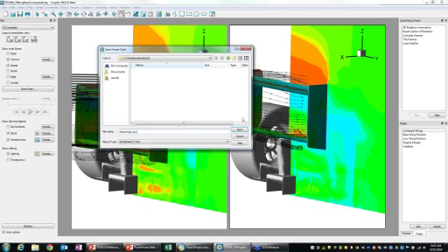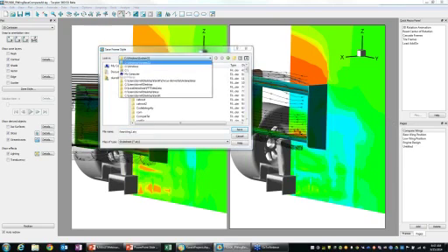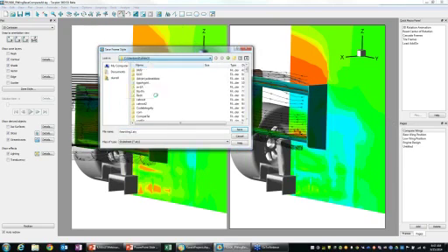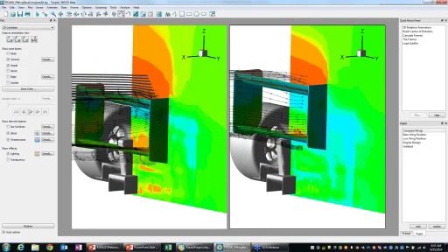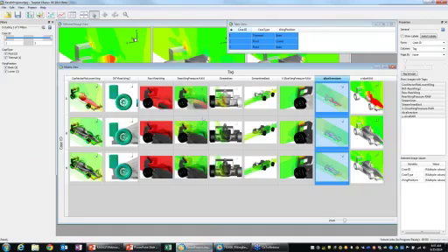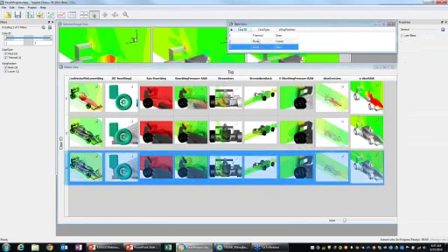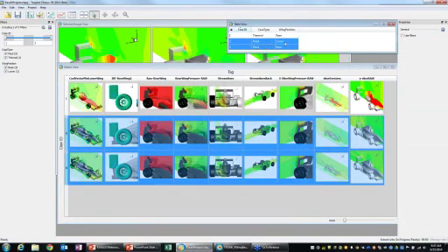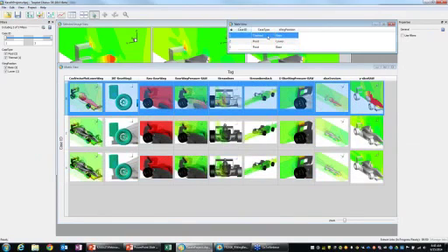But as you know, we're looking at 3 cases, and although I could set most of this up in batch, if I want to evaluate each of the 3 models in context, I can use a tool called Tecplot Chorus. And so I want to show you quickly how that works. So these are the 3 cases, and basically we have the 2 cases which are purely looking at rear wing position. And we also have the case which is the thermodynamics with the engine, which is reading heat at 500 Kelvin.